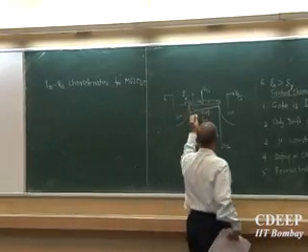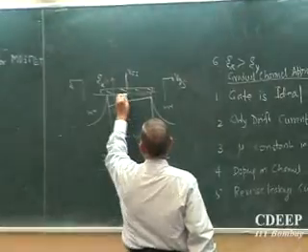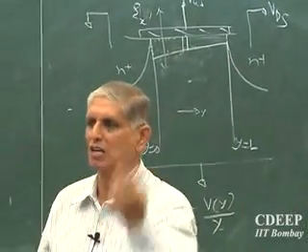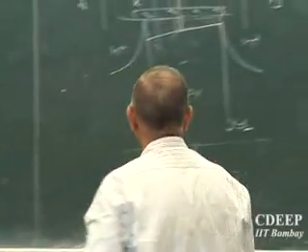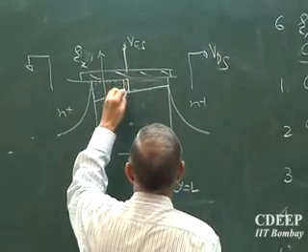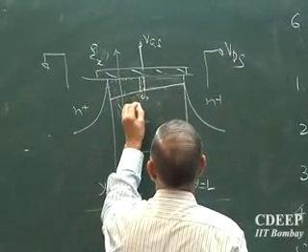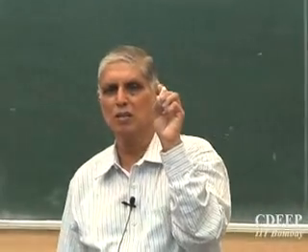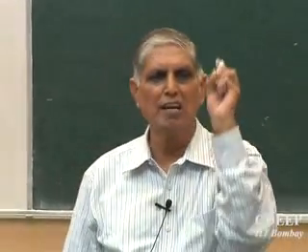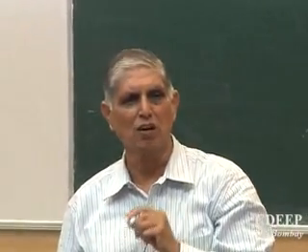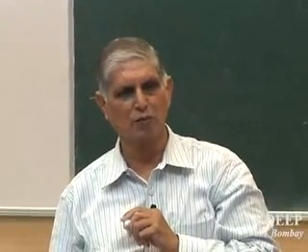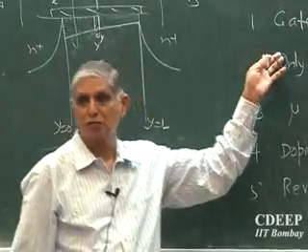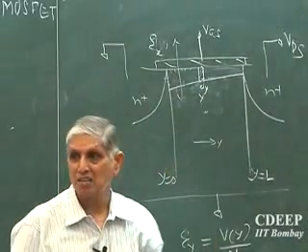Let's take the inversion layer, which is trapezoidal, as shown right now, and we have an element of dy at y. At any position on the channel length, there is a point y at which I am taking an element of the channel which has a thickness of dy. Is that correct? Since I already said only drift current is flowing, this is acting like a resistor.